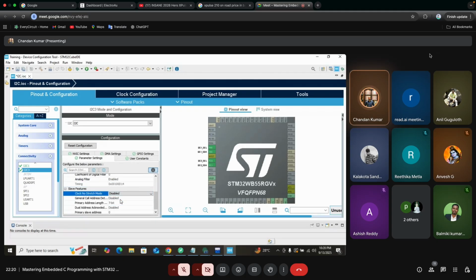That will be disabled. Here, I'll give this 12. You can give any slave address. Just make sure your master transmits to the same slave address.